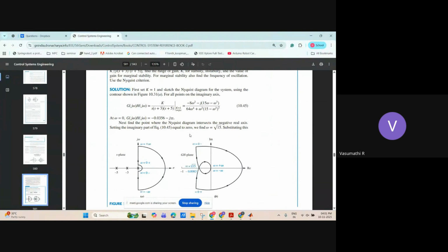So we will calculate it by hand and also by this. The MATLAB keyword for Nyquist is nyquist(G1). As we did for root locus, it is rlocus, right? Similarly, for Nyquist, it is nyquist, same word. We will plot both Nyquist and root locus. This figure command will create an environment for this. If you plot only one figure, you don't need this. If you plot multiple figures, you would need this to separate those.